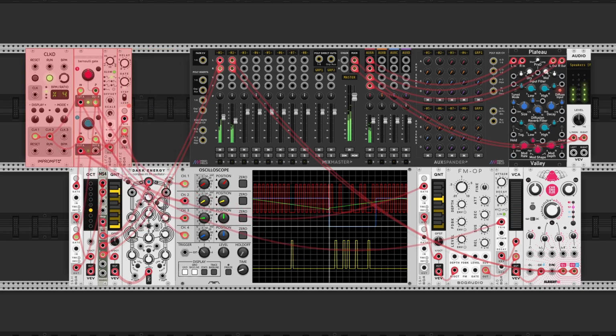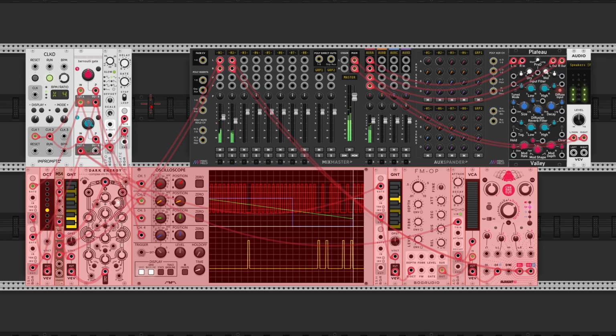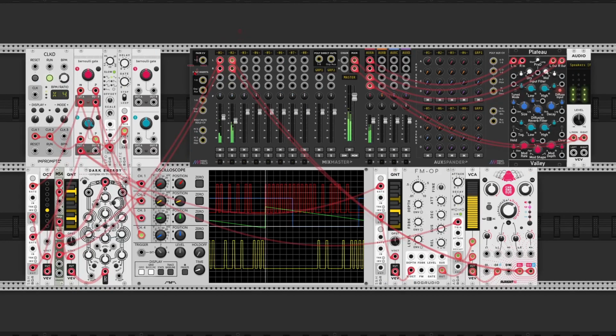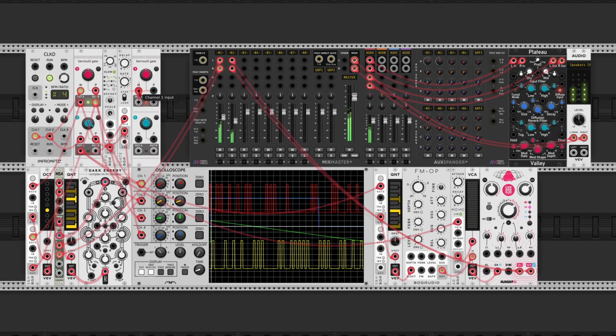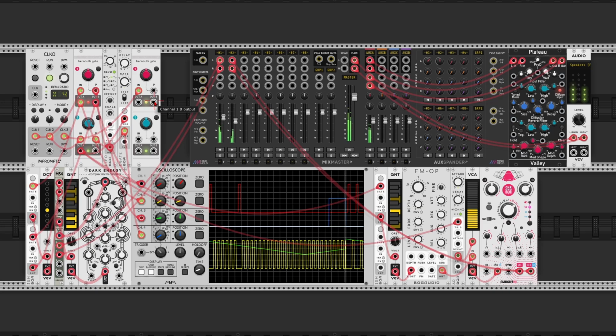Also move this bottom row, and add in another Bernoulli gate. Click this button to switch it to the other mode and hook it up to the third clocked output. Now the outputs will switch between 0 and 10 volts at random times when a trigger is received.